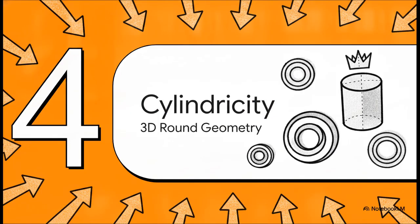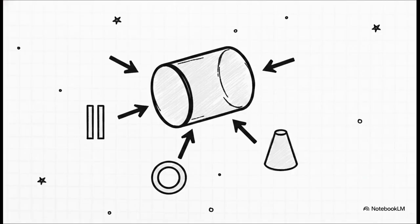Number 4, cylindricity, 3D round geometry. To catch that barreled or wasted defect, we have to move to the bottom right of our matrix and unleash the absolute boss-level 3D symbol for round geometry. Cylindricity is the one symbol that practically everyone underestimates, but manufacturers respected deeply because it's a strict, all-encompassing control. As the ASME standard explicitly points out, cylindricity is a massive composite control of form that commands three things all at once: the straightness of the cylinder, the circularity of the cylinder, and the taper of the cylinder. It evaluates the entire feature at the exact same time.